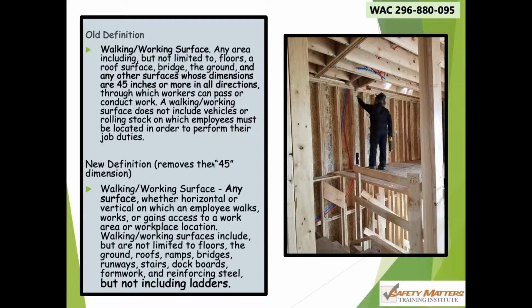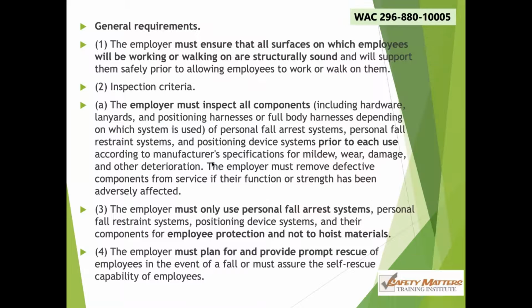And with those last 4 little words, the construction industry breathed a huge sigh of relief: but not including ladders. So 45 by 45 is gone. It's now anything that I can work on, walk across, pass along, stand on, do my job from. It doesn't matter how big or wide it is. If I can do any of those activities, it is considered a working walking surface, but not the ladders. Oh, thank goodness for those 4 little words.